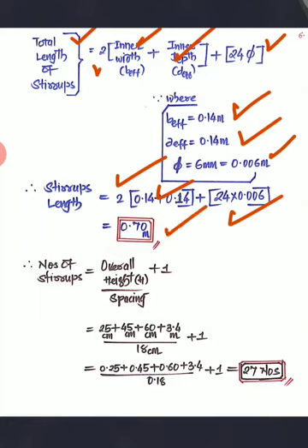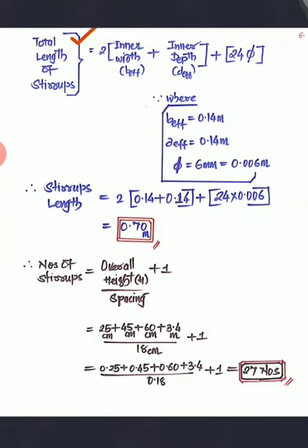Now you are supposed to determine the number of stirrups, as that number is not given in the problem. So take the overall height divided by the given spacing, plus 1. If you do this, you will get the number of stirrups. You are supposed to start from the tapered portion, as I'll show in the figure.